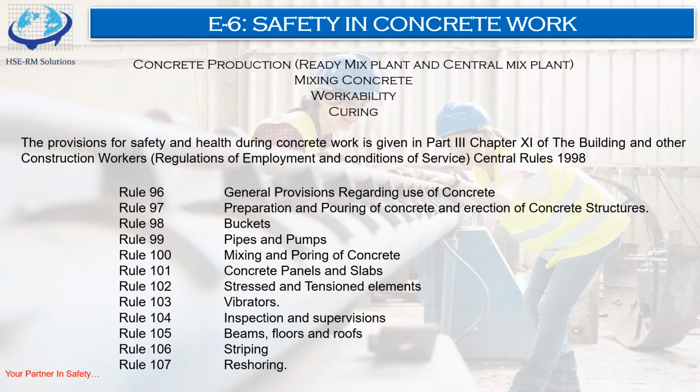Workability depends on water content, aggregate, that is the shape and the size, cementitious content and age, that is the level of hydration in it. It can be modified by adding chemical admixtures like superplasticizer or resin, or by adjusting water content, increasing the concrete workability.